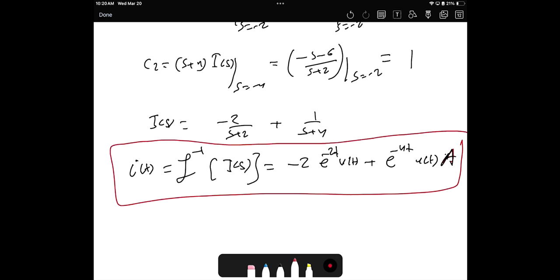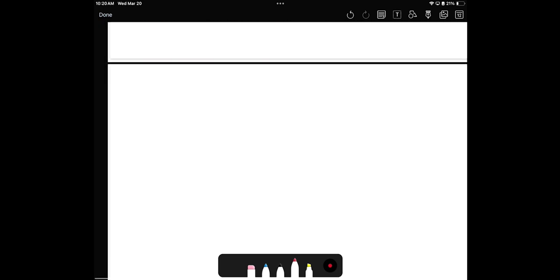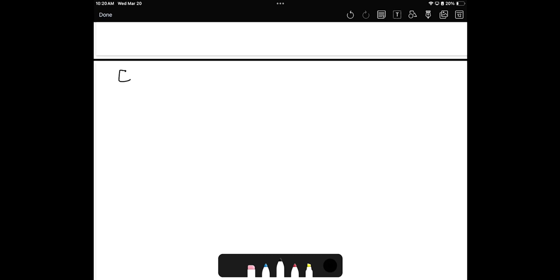So we solved this circuit without worrying about the complexity of the differential equations or about what we've learned before in the transient, while we can do it in the s domain. And again, this is applied on DC, we can do it in AC. But most likely, if we do it in AC, we might get more complicated sinusoidal forms. But we can still handle it. Just do the partial fraction expansion with the conjugates, and it should be fine. Okay, let me do more examples so we can be professional on it. The more you practice, the easier it will be.